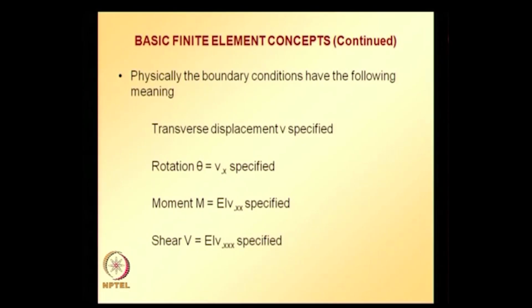to solve this problem. And looking at this physical meaning of the terms, the boundary conditions involving V and derivative of V are essential, and the boundary conditions involving second derivative of V and third derivative of V are natural boundary conditions, and this can be verified using the thumb rule that I gave in the earlier classes.